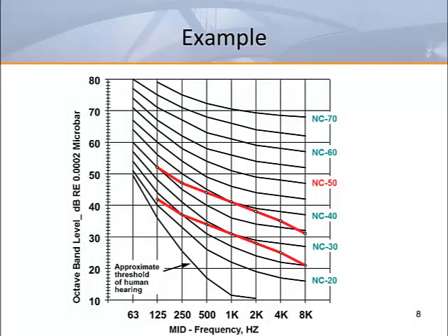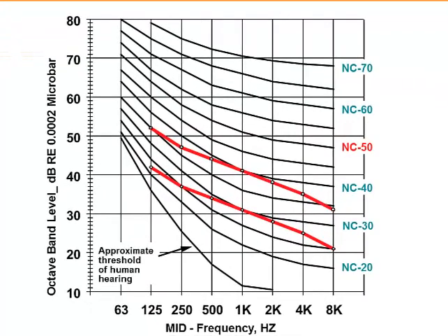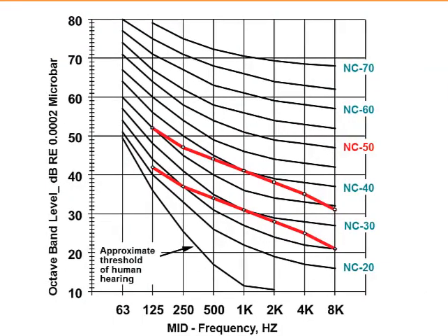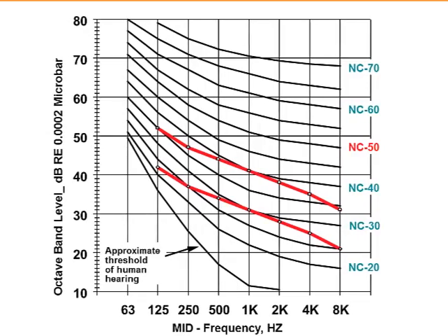Manufacturers must produce performance data that meets industry standards and will be useful to engineers and designers. If a diffuser is tested in a reverberant chamber, the sound pressure will be measured and the room absorption will be added to calculate the sound power at a given flow condition. If that sound power were plotted on an NC chart, it would look like the upper red line. According to the chart, the best sound level is in the 1000 Hz or 5th octave band, making it the critical band that sets the overall sound level of NC 40.